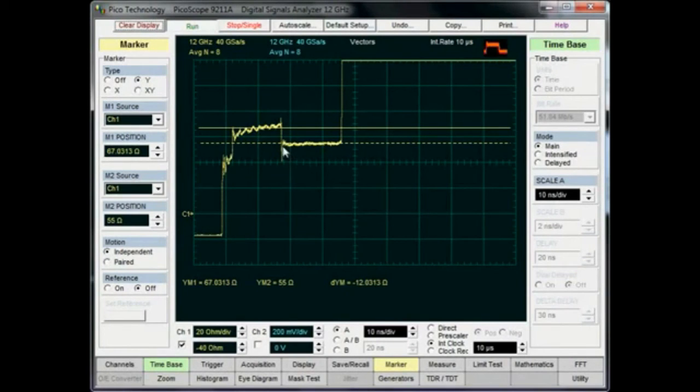As a final example, at the T-piece now I'm going to put in parallel a second piece of 50 ohm cable in parallel with the first piece. Obviously the effect of that is to lower the impedance. Two 50 ohms in parallel will give me an impedance of 25 ohms. So here I can move my cursor down now, and indeed the parallel of those two pieces of cable gives me an impedance of 29 ohms.